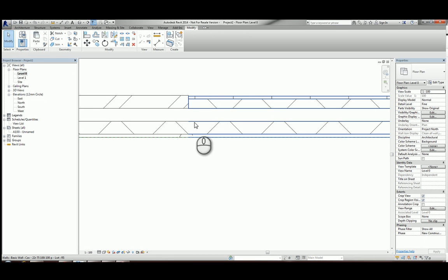So later on in a project, once your engineer has done all of his structural setting out, once you've got it set out on site, once all of your brick dimensions have been done, really you don't want your external and your masonry part of your wall to change. Who cares really if your plasterboard just squidges in by a little bit? So let's have a look at what happens in this case.